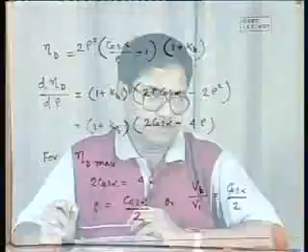I told that V1 comes from how much enthalpy drop we are going to allow in the nozzle. So, if V1 is selected independently, then Vb bears a relationship with it for maximum efficiency, and this is the relationship.